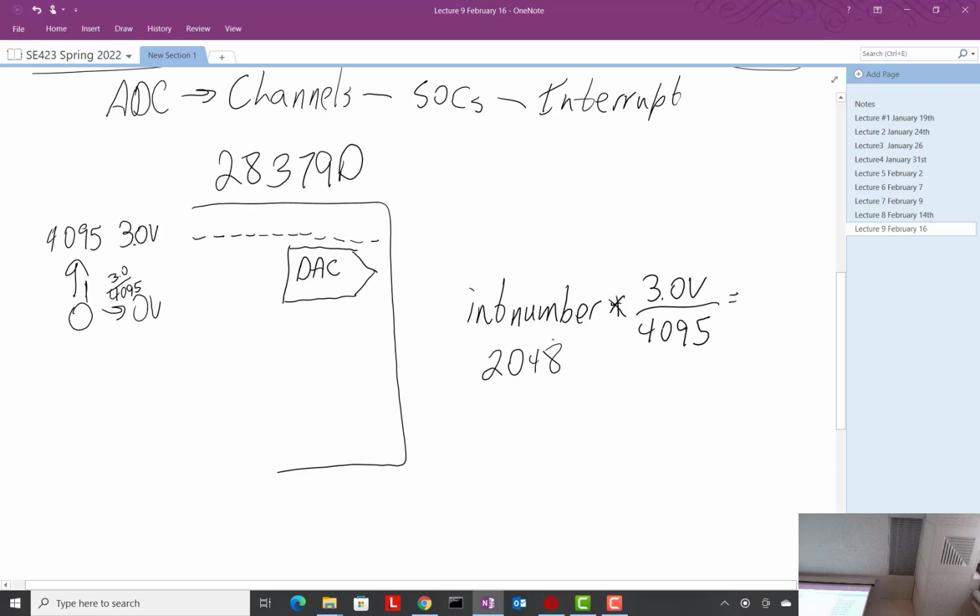Well, yeah, just one second. I'm getting a little ahead of myself, aren't I? This outDAC function that we're going to be using is not until next lab, lab 4. We're not going to be using it in lab 3. Sorry, a little bit ahead of the game. All we're dealing with in your homework number 2 is the analog input. I'm jumping ahead a little by talking about this DAC, but it helps to talk about it first. You'll see that we're going to write a function that, given a voltage, a number between 0 and 3 volts, we can scale to a number between 0 and 4095.